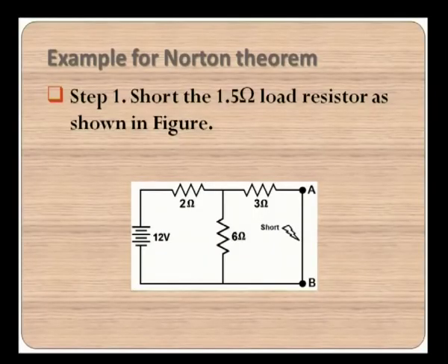So, let us try to use the Norton technique and replace the remaining part of the network across AB with the Norton equivalent. So, the equivalent circuit will become very simple. There will be one current source and one resistor in parallel across the current source and again the load resistor, of course, which is an external part as far as this analysis is concerned. Now, let us see how we approach this problem step by step.